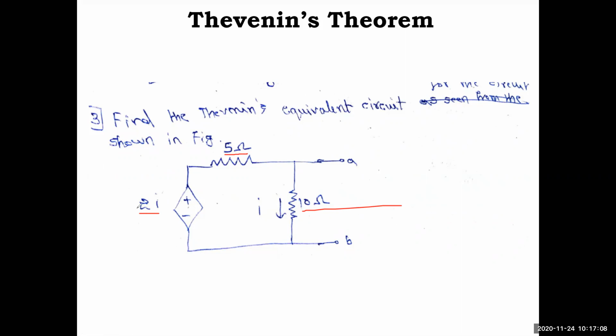Fine. So what is the type of this voltage source? Dependent voltage source. It is a voltage source that depends on current. That's why it is a current controlled voltage source. Whatever classification it may be, we are not bothered about it. So now VTH is 0. So we will connect a 1 amp current source here and measure the VAB, or else a 1 volt voltage source and measure the current IBA. That step I will show you next. So hope you have noted down this question.